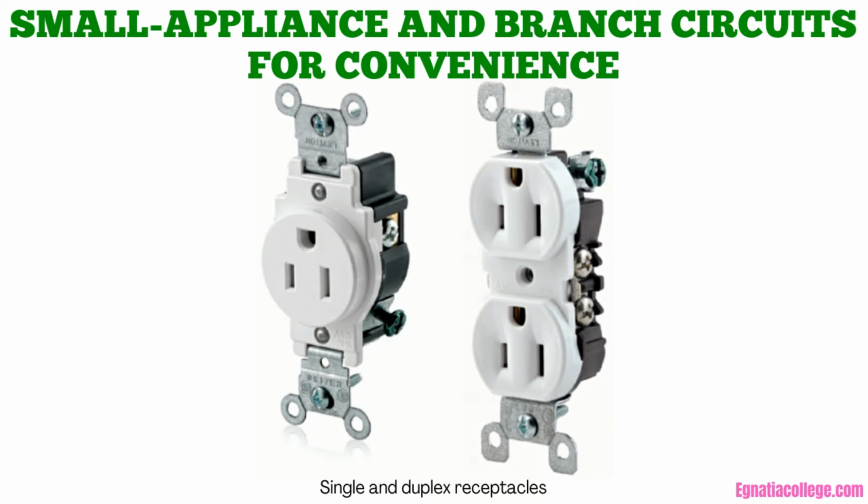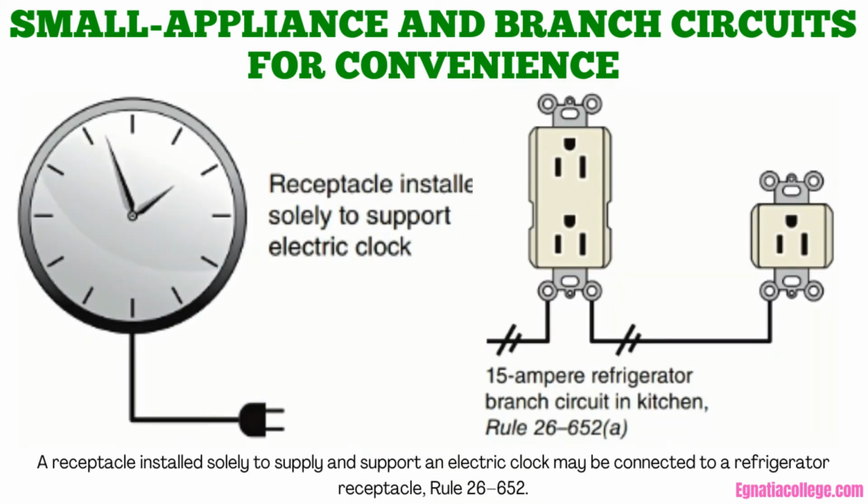Receptacles may not be either directly behind or in front of the sink. The clock outlet may be connected to the refrigerator circuit only when this outlet is to supply a recessed clock receptacle intended for use with an electric clock, Rule 26-652. In the residence in the blueprints, the clock outlet is connected to the lighting circuit.